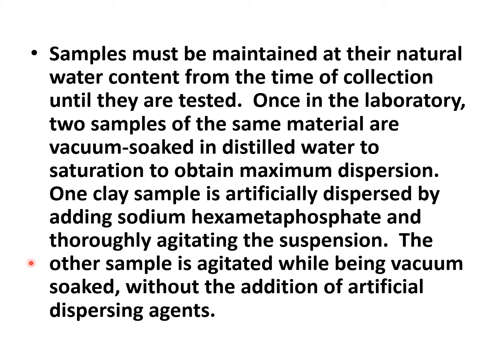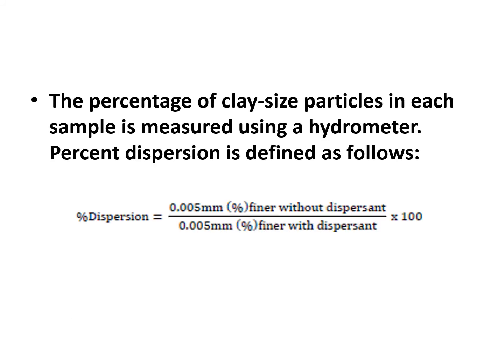The other sample is agitated while being vacuum soaked without addition of artificial dispersing agents. The percentage of clay-sized particles in each sample is measured using a hydrometer.